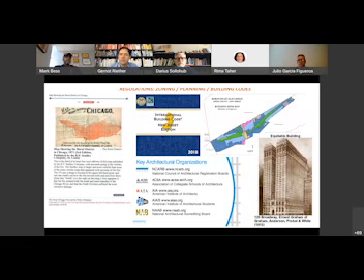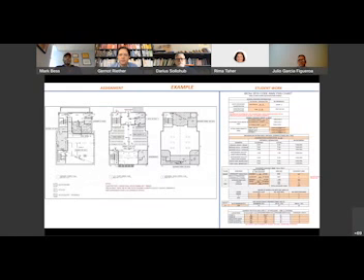And then we take a deep dive into building codes for several sections. The first section looks at the history and background of building codes as they were developed over time. And then we take a longer look at codes in general. Here's an example of an assignment related to building codes. I'll give them a series of floor plans, and we'll talk about egress and how we can calculate travel distances, occupancies, occupant loads, egress widths of stairs and corridors, allowable heights, and allowable stories based on use group and construction type.